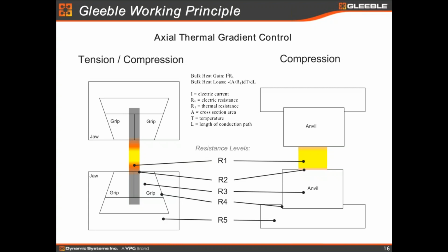That's why the Gleeble is different. An MTS is so easy, so slowly doing. Everybody can do it. But when you are running at something like 2 meters per second, it's not that easy because you have to control well, right? But the principle is very simple: just tension and compression. Or if you need to do torsion, we can put a hydraulic torsion motor on it.